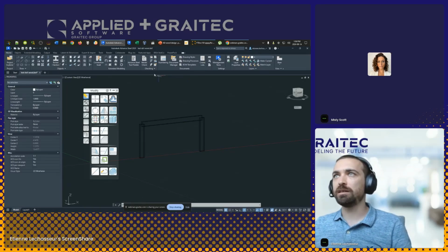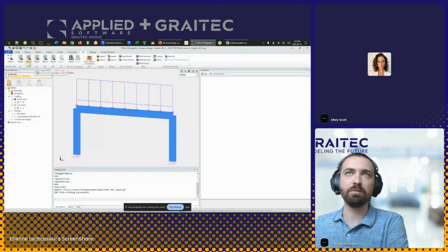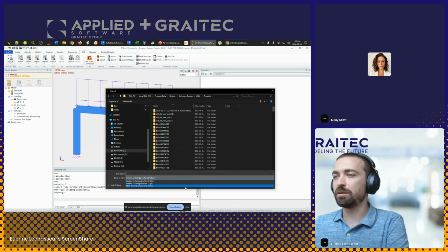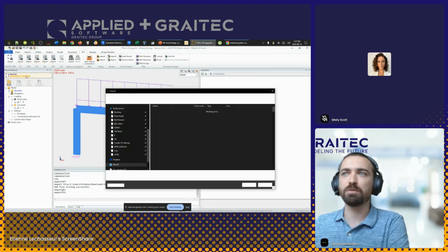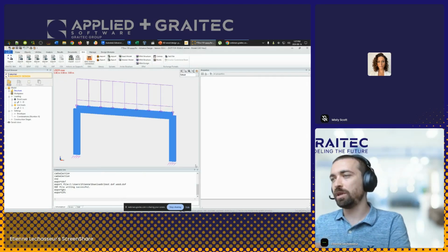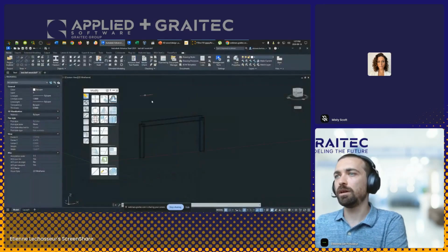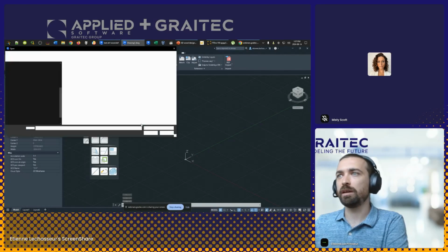So I'm using Advanced Steel right now. This is a software that is able to import IFC format or many other BIM formats. With Advanced Steel, for example, it would be with the SMLX format, which is typically the best one, or as I said, just the IFC. Typically, it works pretty well. So you would export the IFC, and then you would have to import it into your software. So if I go to a new file, this would be import export, import IFC.